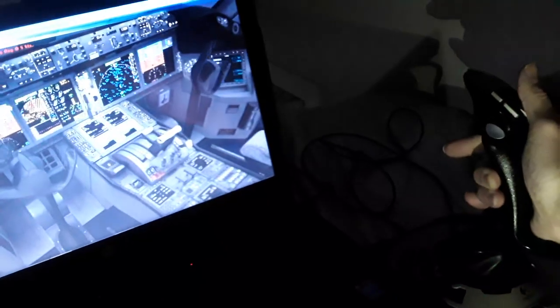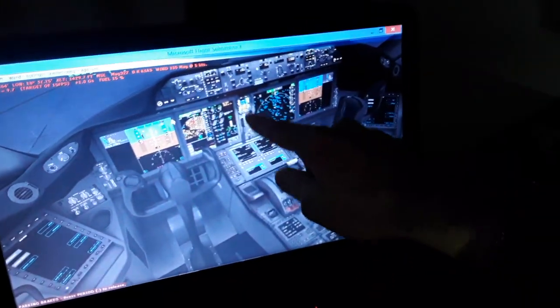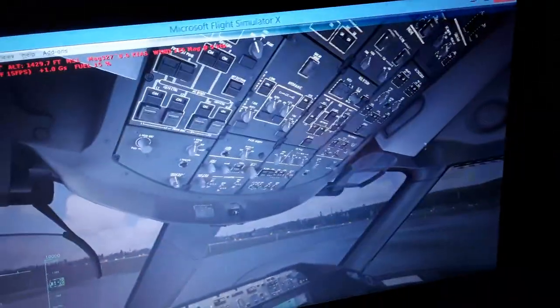We have also the air conditioning, ventilation, and hydraulic fluid tanks. The engine pressure also pressurizes the hydraulic fluid tanks. Also we have the wing and engine anti-ice, and also the hydraulic fluid tanks that pressurize the flight control surfaces. For instance, the thrust reversers for the engine, landing gear, retract, parking brakes, rudder, all flight controls you see. Also we have the FADEC control, the fuel recirculation from the left and right wing in flight to heat up the fuel so it won't freeze. Also the lubricant and the oil, we have the recirculation of the fuel system.